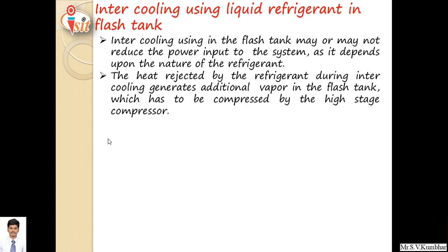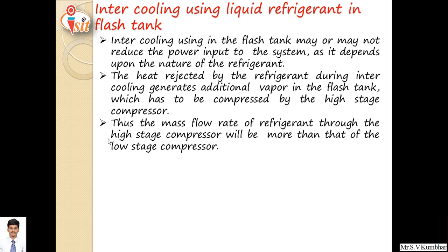So intercooling using the flash tank may or may not reduce the power input to the system, as it depends upon the nature of the refrigerant. The heat rejected by the refrigerant during intercooling generates additional vapor in the flash tank, which has to be compressed by the high stage compressor.